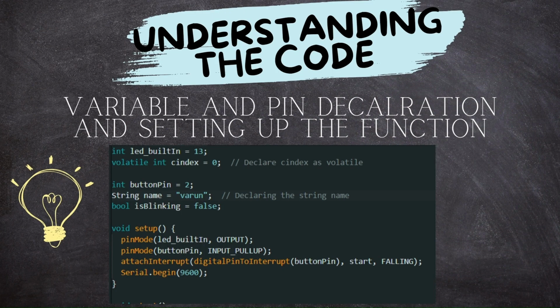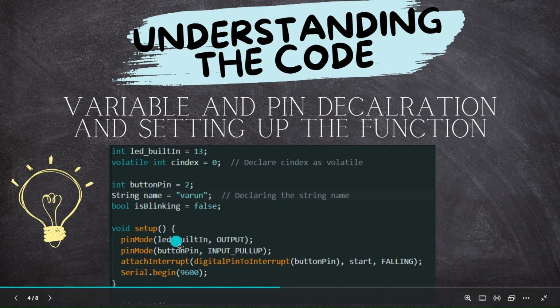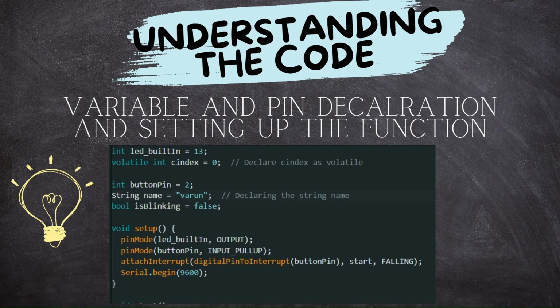Now, let's understand the components of the code. In the variable and pin declaration, we declare the variables for LED control, character index, button pin, and more. Basically, we have declared our built-in LED on pin number 13. In our setup function, we configure the LED and button pins, set up an interrupt on the button pin, and initialize the serial communication.